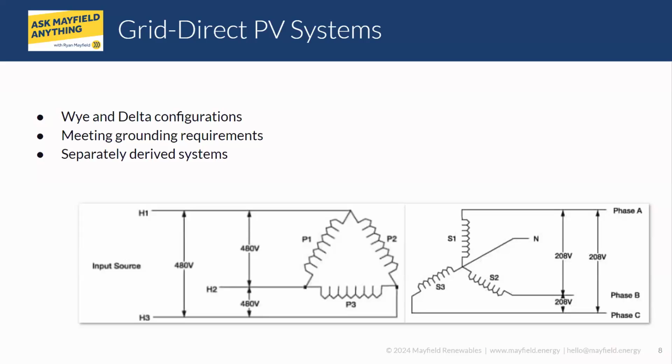And I believe, Medina, when you get into some of the things on the rectifiers and the battery storage systems, that'll come up a little bit more. But sometimes, even if it's a 480 to 480, if it's providing that isolation, it does protect the system. So that's important. It also gives you the opportunity, as you're seeing here on the Delta Y, to have a separately derived neutral.